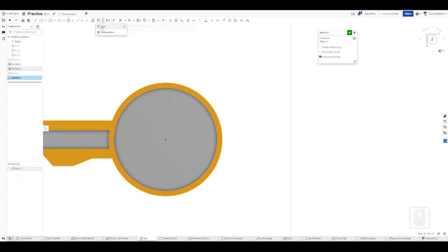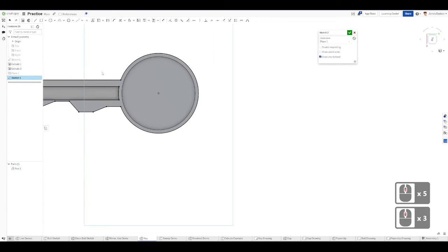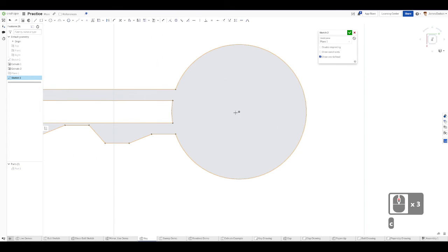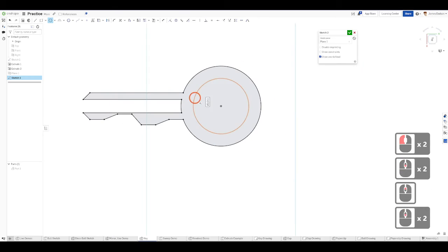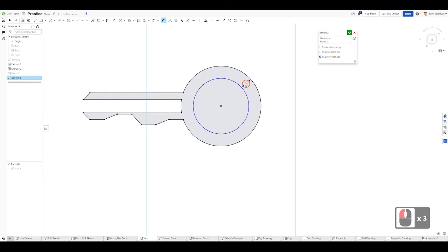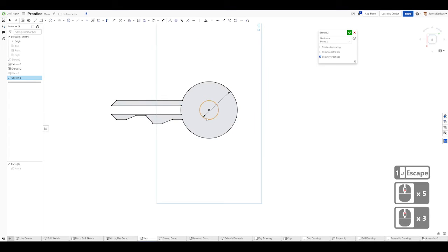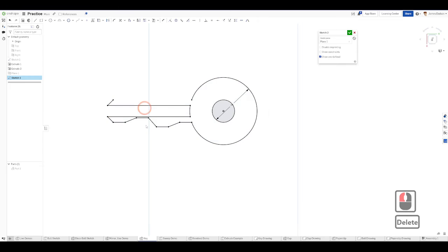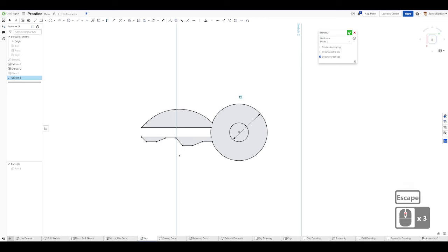It's one of these. This one up here. Use. It looks like a little box. If I press that, you can now see, even if I hide the part, all the geometry's been copied over, and now I can add additional stuff on top of it, and modify it to suit whatever I'm trying to do, right? So this is an easy way to quickly modify parts and stuff.